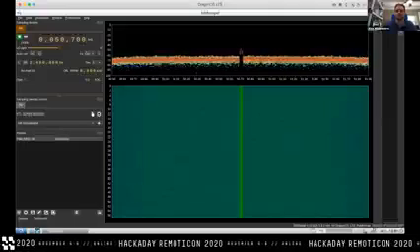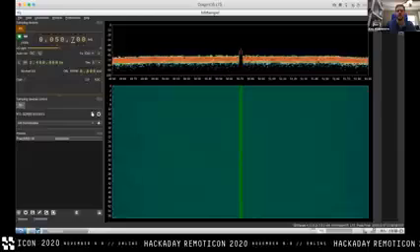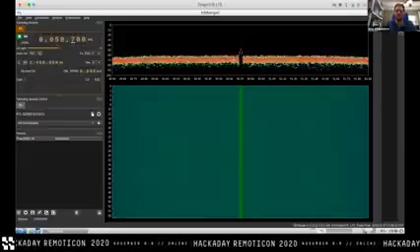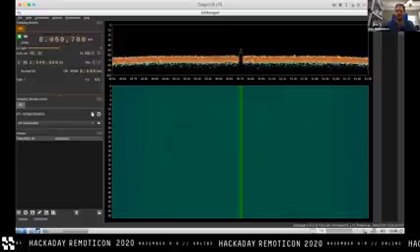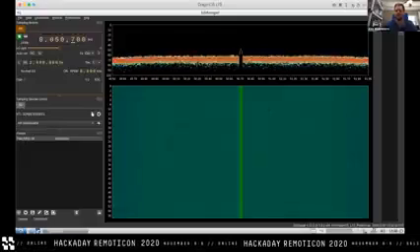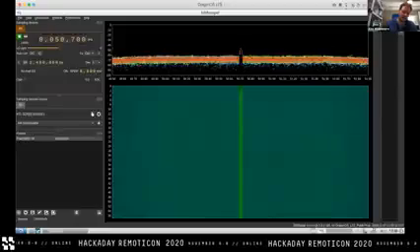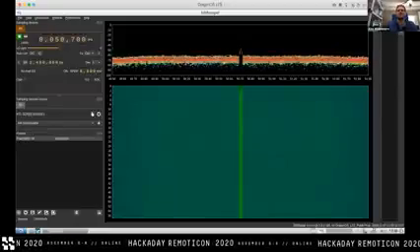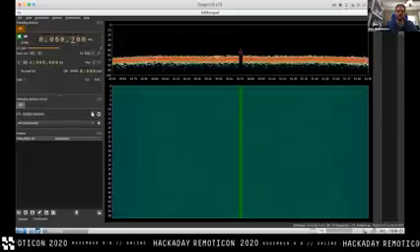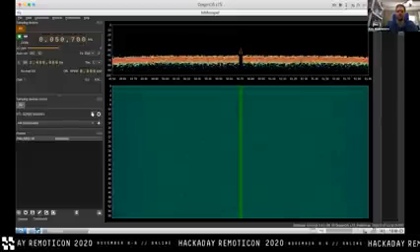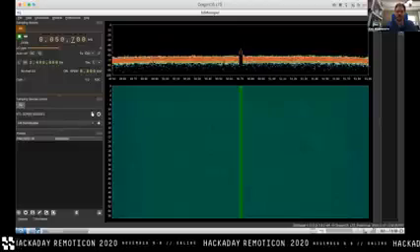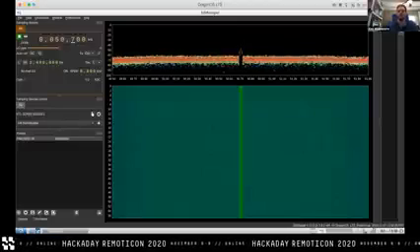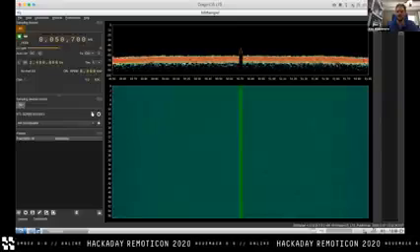It is useful for something like ADSB, which has a much narrower signal bandwidth and is at a much lower tuning frequency. I don't even remember what it is, like 1064 or something like that, 1.064 megahertz. Anyway, for our purposes, the tuning band of interest for this test report I just showed you is 30 megahertz to 1 gigahertz, which the RTL SDR covers nicely, so it's useful for that. And the question that really remains is, how do we get better bandwidth to actually cover that whole span?